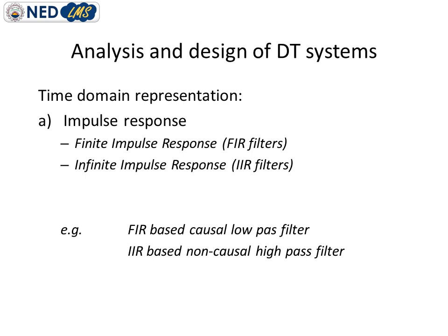Or in other words, FIR systems are those systems whose current output, which is the present output, does not depend upon the previous output samples. So both definitions are valid. In terms of impulse response, FIR filters are those whose impulse response exists for a finite duration of time. Or in terms of output, a system whose present output does not depend upon previous output samples is termed an FIR filter.